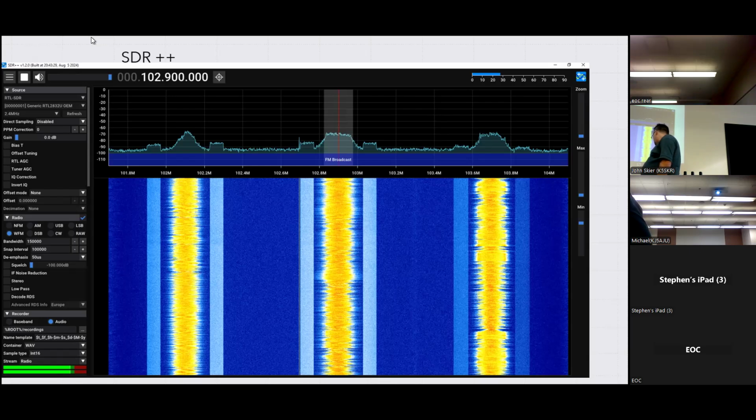Mike, I assume all these, if you click on the waterfall area, it'll switch. Yes, if you have real time, and we'll play around with some live here in a little bit. Real time, if you click on the waterfall, you can actually switch to where that signal is. So if you're working HF and you're looking at the entire 20-meter band, trying to find somewhere to work, you can double click on the signal that's in the waterfall to find out what's there. And then if that's something you want to work, you can then turn your radio into it.